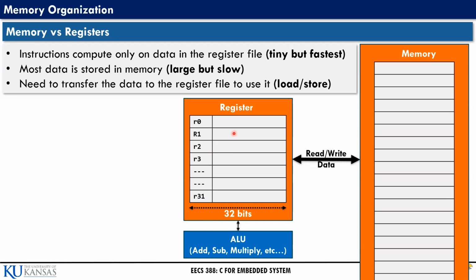Registers are made from flip-flops, and each flip-flop is basically a collection of transistors. So if we increase the size of the registers, we are basically adding more flip-flops, which in turn significantly increases the number of transistors. This not only requires more physical space on the CPU chip, but also increases the complexity of the CPU design.